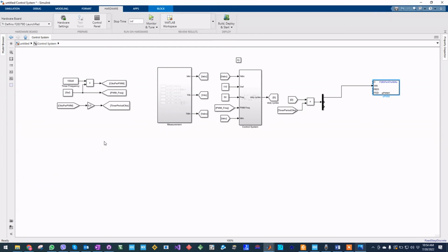For the deadband we have to do some computation because we want to change the deadband from here. We will set the deadband to 2 microseconds from here. We will use the timer clocks to compute the appropriate number of clocks for the deadband. For doing this we will divide by 2e power minus x, or we can multiply this with the frequency.